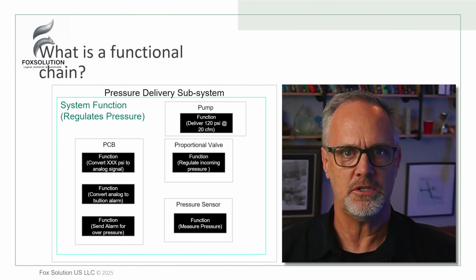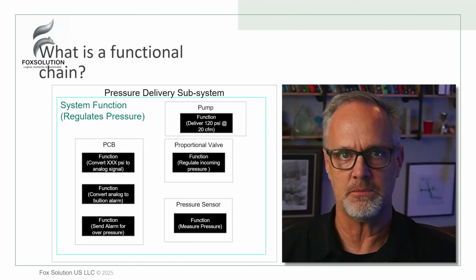Now, one of the problems that you run into in a design is, let's say we're doing risk management. And one of the designs I worked on in the past is a system that fixates the eye. And in that case, it would be vacuum that we're trying to deliver. Well, we identify the fact that if we put too much vacuum on the eye, we rupture the globe. So we have a much higher risk than we originally had anticipated. What we want to do then is sort of deepen the level of our understanding of our control of this regulating pressure function. And in this case, what we're going to do is build it out into a subsystem so that we get better control.